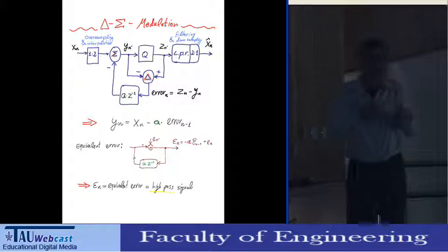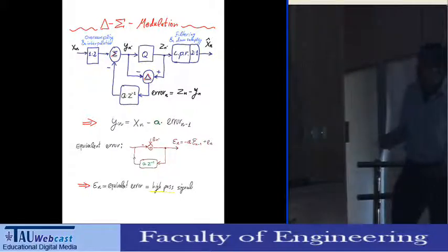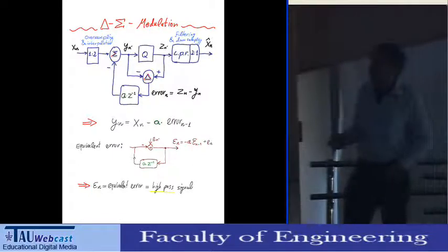I'm willing to spend more on sampling and less on doing A to D. And a simple way to present this idea, which is called, by the way, delta sigma modulation, is in this picture. So I'm taking a source, I'm oversampling it, so now I'm having samples which are faster than Nyquist.